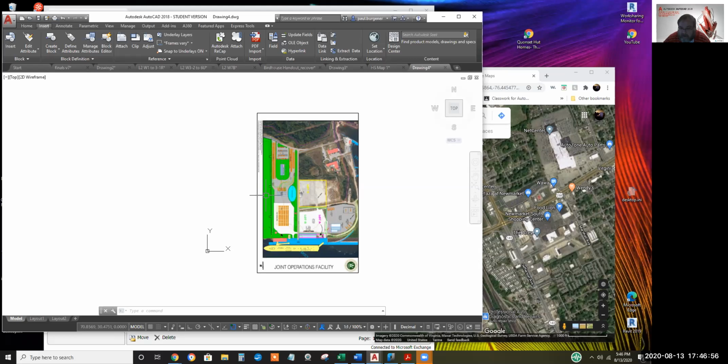So it's kind of like a reverse engineering tool. If you've got a broken part in the field and nobody can find the drawings, you can scan it, scale it, and trace it in AutoCAD and develop the manufacturing drawings just out of the scan, scaled to full size.